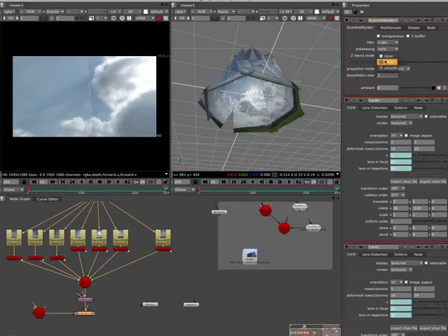So if I turn on the Z blend mode, the thing to remember here is that it is referring to the same scene scale units as my 3D view. Now I've scaled my sky dome up by 10,000. So a Z blend range of 0.1 is not enough to function with what I'm going to do. If I kick this up to something more reasonable like 250, you can see that it's going to blend between these two plates and whiz bang, the seam's gone. So now my sky dome has a nice smooth transition on it, right?